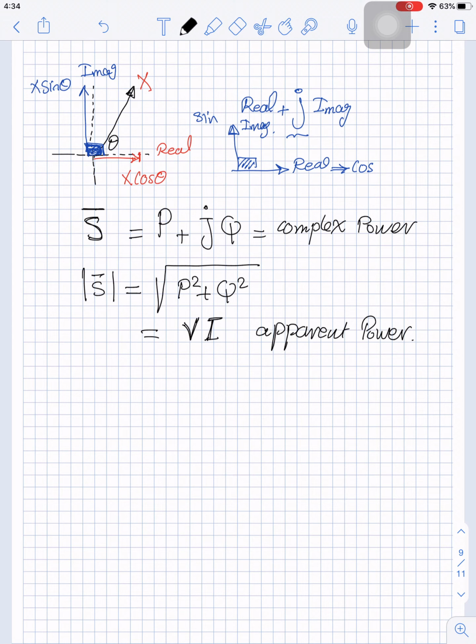Yes, we can measure the active components, like if you have a force at 45 degrees and you need to measure its X component. You can measure it, but physically, you have a force which makes 45 degrees. If you have a force of 10 Newtons at 45 degrees, you can say it has a component in the x-axis and a component in the y-axis. You do these projections or this analysis so you can analyze the system. But what you have physically is a force of 10 Newtons at 45 degrees. So in the system, we have P of t, the instantaneous power. We think about it as two components, one active and one reactive. Why? Because for the active component, we can calculate how much power is productive and will be an output. And the reactive component is just power going back and forth between the supply and the source.